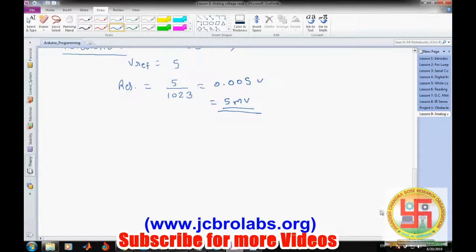Okay, so in Arduino it is very easy to read any analog voltage. Arduino has A0 to A5, that means a total of 6 channels, 6 ADC channels. That means we can connect 6 different analog sources if we want to convert them with the ADC. So any specific channel can be connected to any analog voltage source, right?